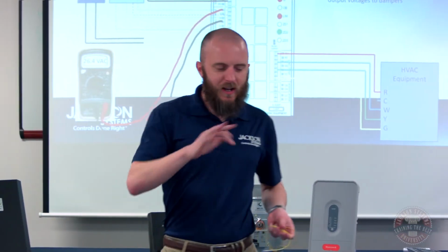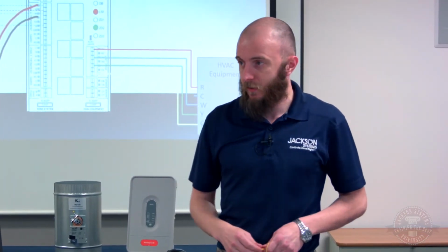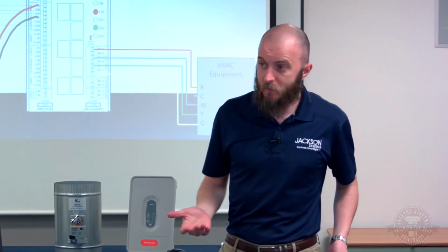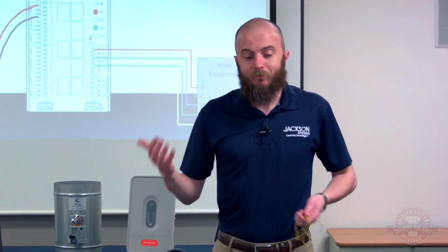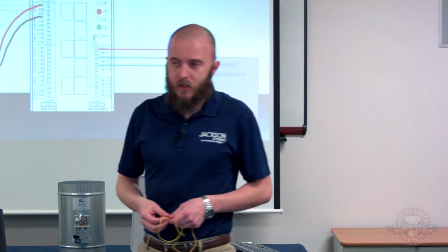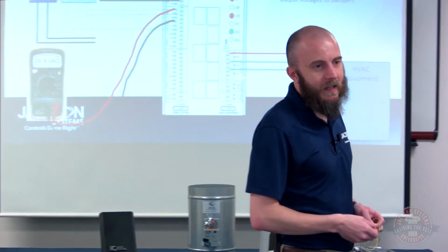But you've got to know how to check it out. On most any panel, you can do that. Simulate a thermostat input and see if it behaves properly, see if it reacts the way you expect it to react. If it doesn't, the problem may be inside the zone panel. But in a lot of cases, it's not.